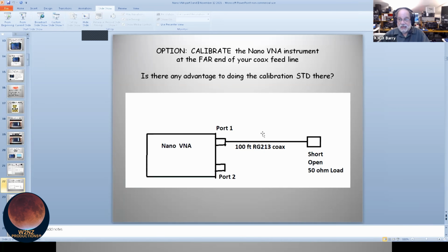I can look at the impedance, the resistance, the reactance in my shack at the end of the cable, or I can say, well, if I took this little device way up at my antenna, what would it read? Here, I can calibrate it at the end of my coax, and what I read in my shack reads as if I were up at the antenna itself. Very, very clever. I can't do that with the MFJ and the Comet meters.